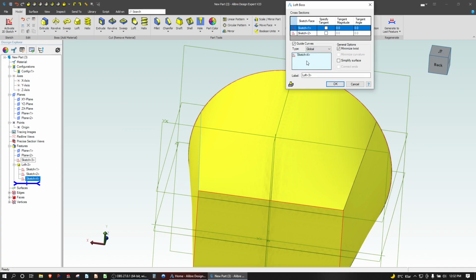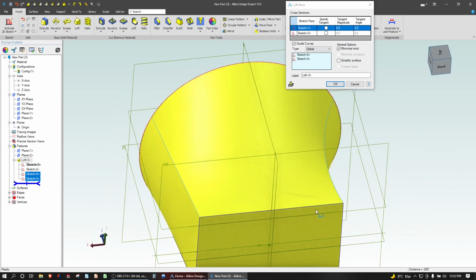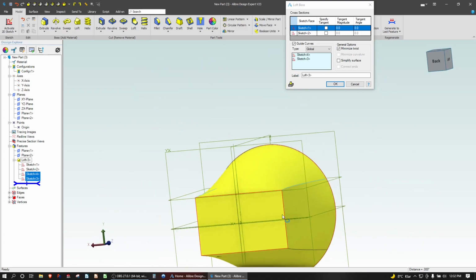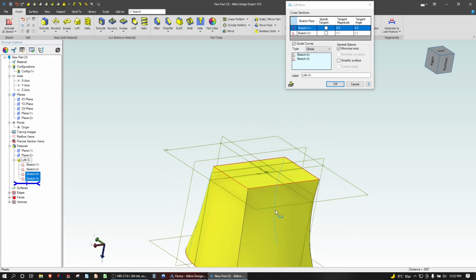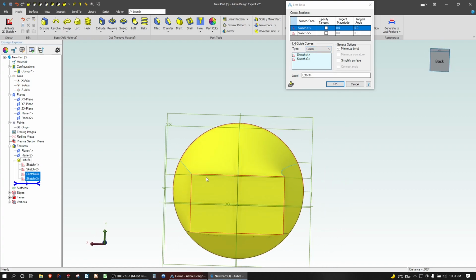We also, let's say we want to add another sketch element, right? We were able to add that successfully. So we've got a curve on one side and a line on the other. Now, this is deceiving because sometimes you may have a failure in trying to add a second line when this is set to global. And if that's the case, or if adding a line somewhere affects everything everywhere else, we can change this to local.